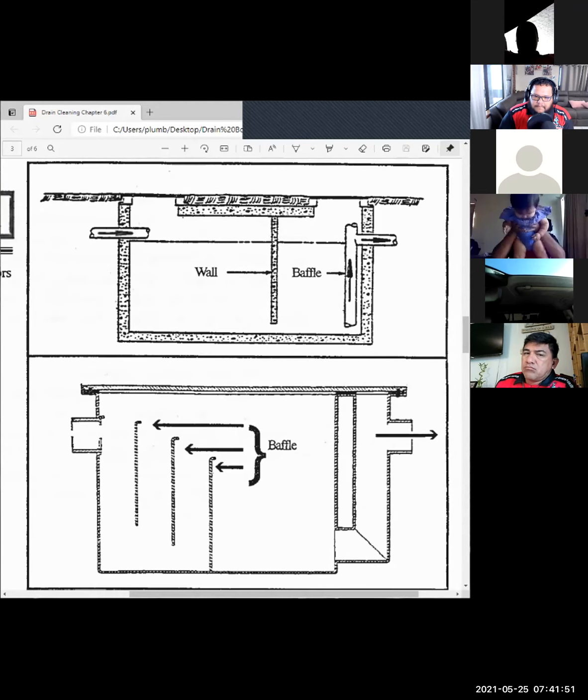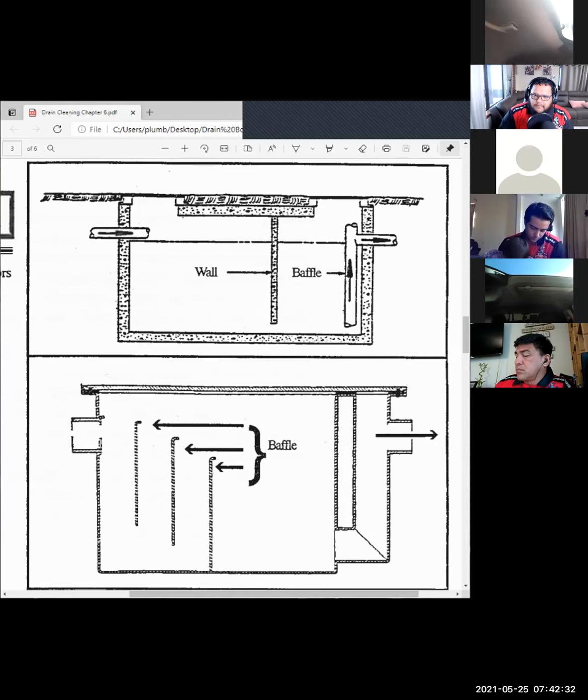There were no grandfathered dishwashers because they didn't exist. If a guy ran a dishwasher to a grease trap, that's just because somebody did it. But the new grease control kitchens only came about, I'm going to say, 20 years ago. At that point, Maui County never allowed the dishwasher to go into them from day one. Oahu did, and Oahu allowed 2,000 gallon grease traps, which is an insane amount of fluid, but that's a whole other story. So if you have a dishwasher backing up and it's suspected to be the grease trap, then it's intelligently tied to it, because it should be, but in Maui County, it's an illegal connection.